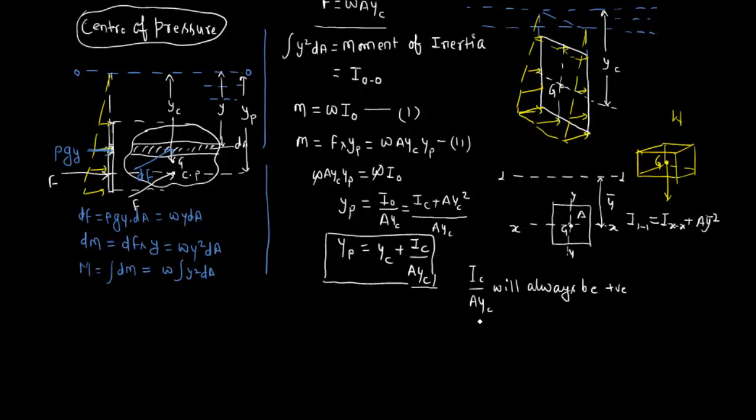If this term is positive, then Y_P will always be greater than Y_C. That means the center of pressure, where the total force is acting, will always lie below the center of gravity of the body.